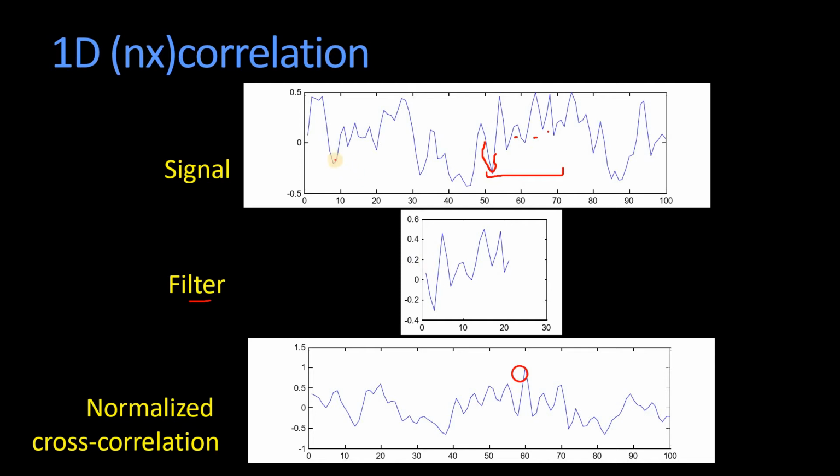Filter is basically a signal. This signal comes inside our main signal somewhere over the time period. The purpose is that I want to find this filter signal inside our original main signal. So what we can do is a cross correlation of these two. I take the signal and the filter, and if you remember, this is the symbol for cross correlation. I apply the cross correlation between the signal and the filter, and it will give me some result.